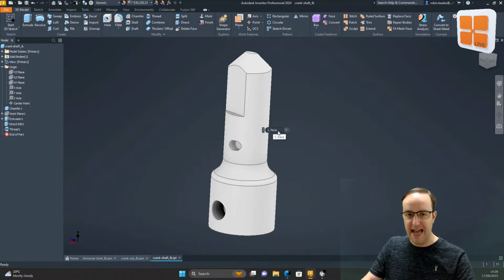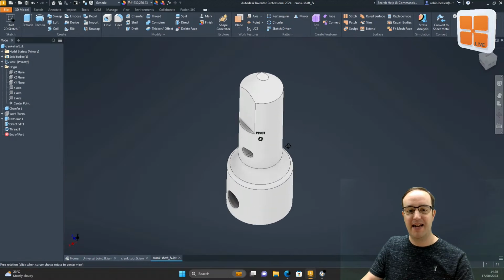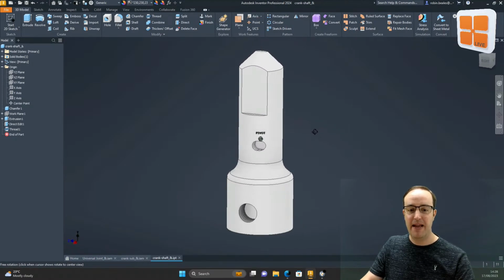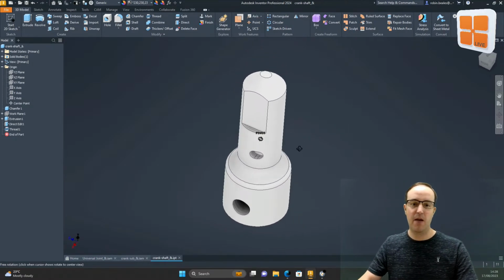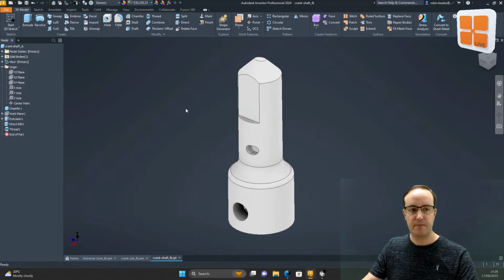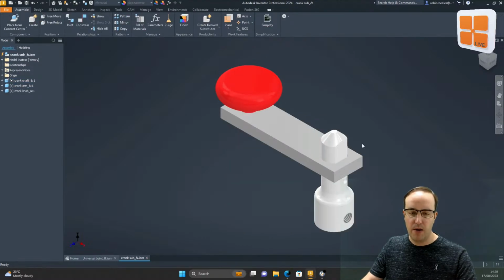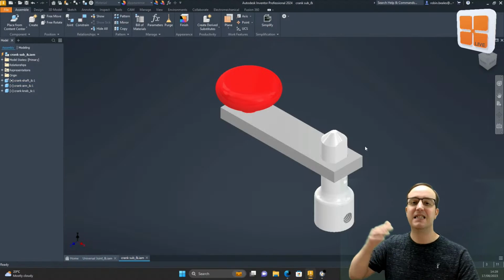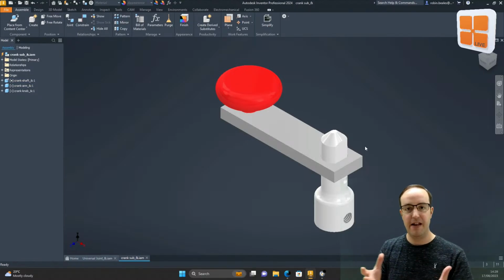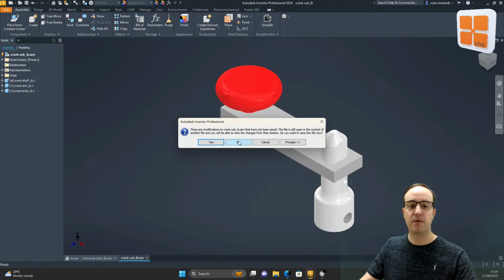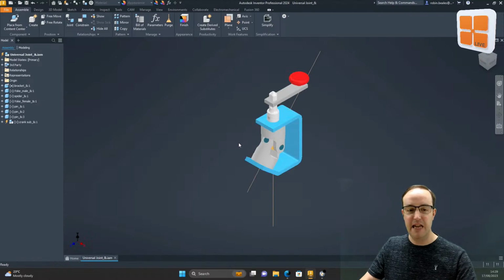It's not just SolidWorks, any CAD system, and we're directly editing it on the fly to make realistic edits that we may want to do in reality. Once we have that inside of Inventor, we can work with it, we can control it, we can create drawings of it, and so on and so forth. It's now Inventor geometry that we can work with and control. So first and foremost, that's really powerful, using direct edit to be able to manipulate and work on the functionality.